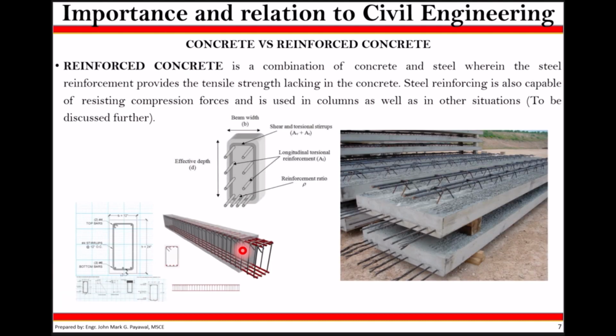a reinforced concrete. Your reinforced concrete is definitely a combination. Is definitely an improvement of a concrete because now it is a combination of one, concrete, and two, your steel, wherein the steel reinforcement provides tensile strength lacking in your concrete. Steel reinforcing is also capable of resisting compression forces and is used in columns as well as in other situations.